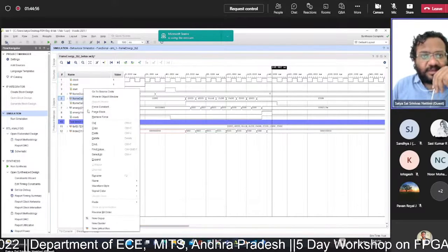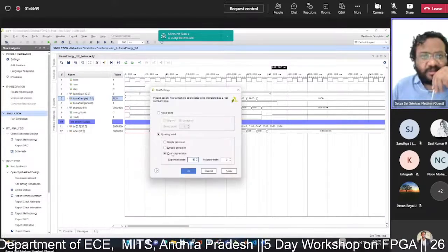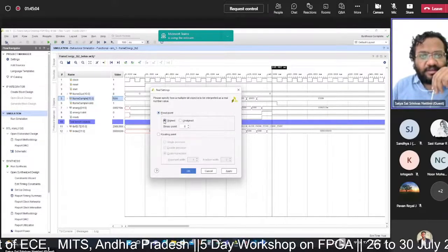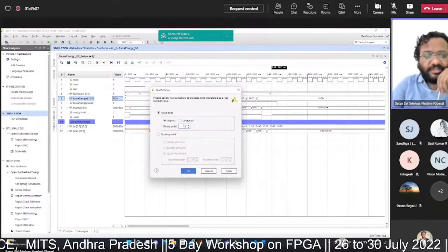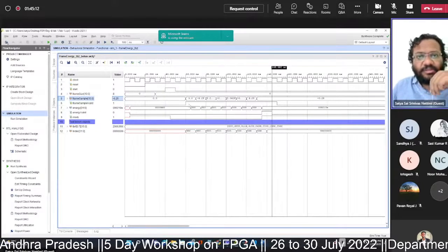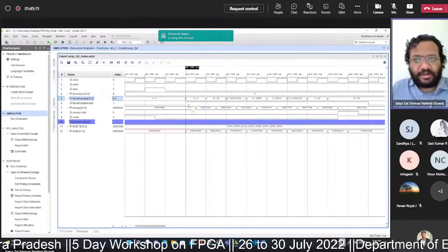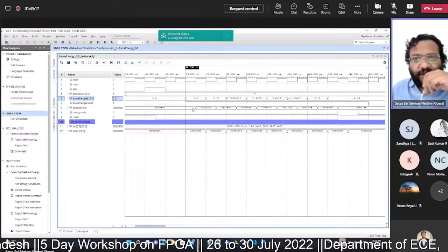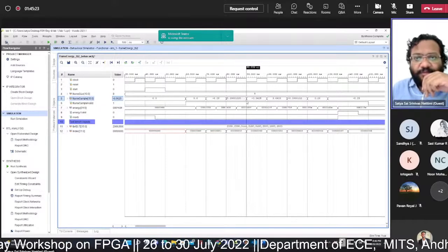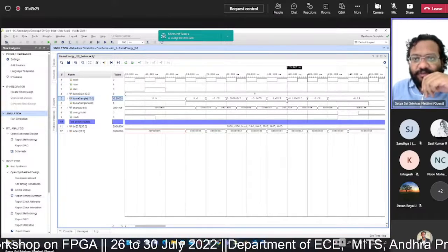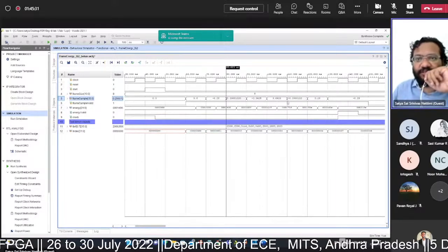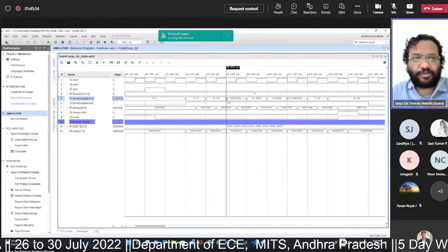Frame sample is a real number, but it is in hexadecimal, so I will change the radix. Click on fixed point. Frame sample is signed, and the binary point is at the 14th bit. Apply and OK. So you can see the values. This time a new set of values, for frame 2: 0.5, minus 0.25, 0.2, minus 0.0625, 0.0625, minus 0.2, 0.25, minus 0.2. Earlier we used two zeros; the two zeros we replaced with 0.4.